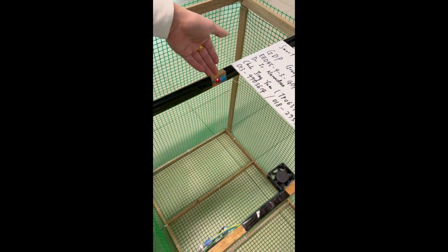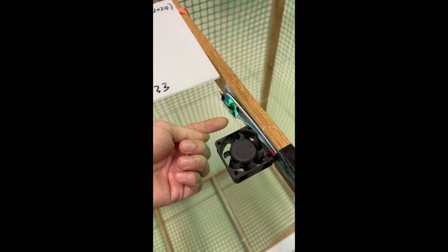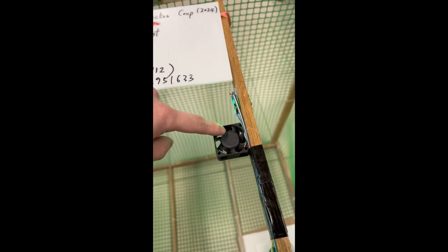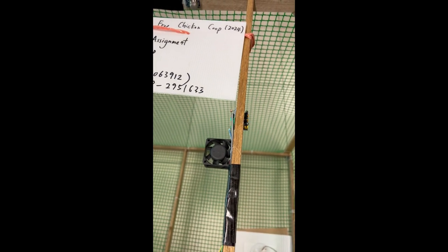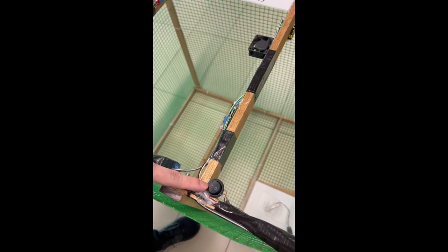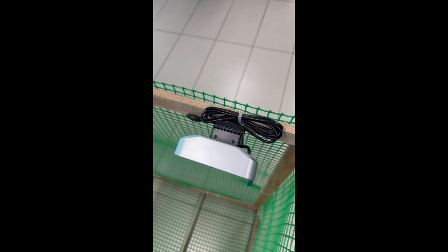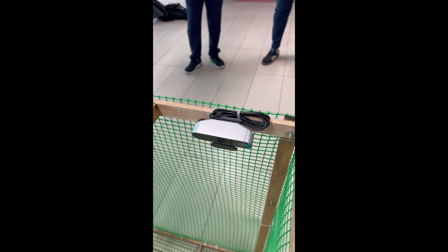So first one is the DHT11 temperature sensors, and in here we have MQ135 gas sensors, and here we have an LDR sensors, and also below we have a motion detector sensors, and here is a little DC 12-volt fan for demonstration purposes of the ventilations, and here is my DC converter, and then here are some of the kill switch, and finally we have a dash cam for the chicken counting by using the YOLO by one of our teammates for monitoring purposes.